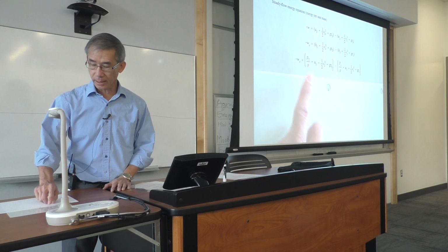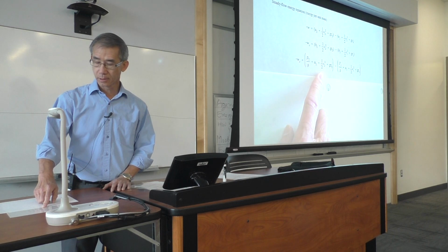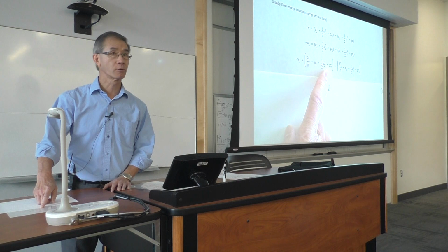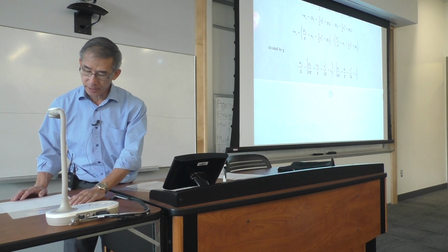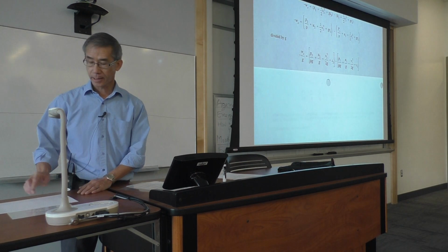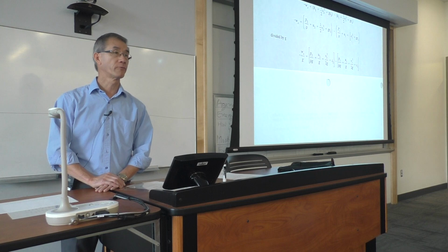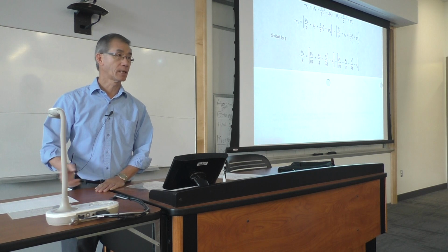So I have now something that resembles where I started: pressure, velocity squared, and the gravitational term. And if I divide everything by g, no change in physics, just the appearance, I have now the equation in terms of height, head, which is what I gave you for the energy equation. And that's how it comes about.